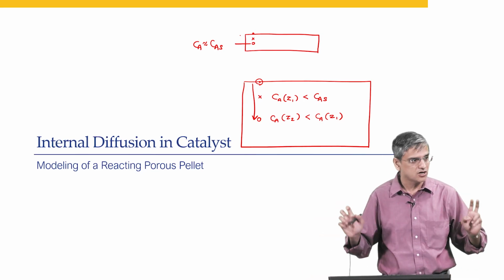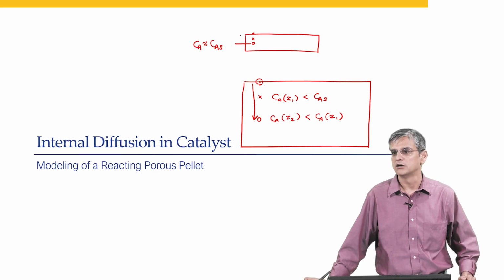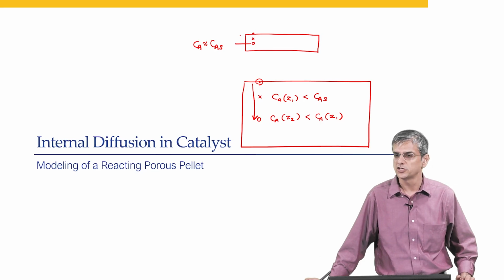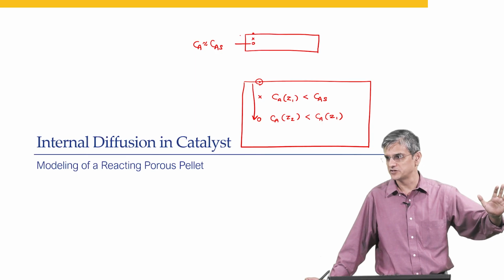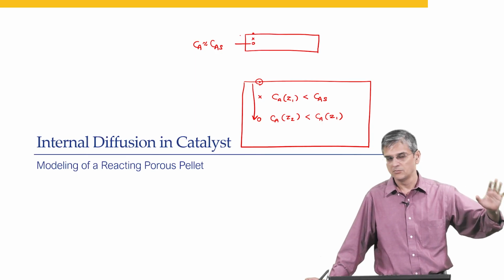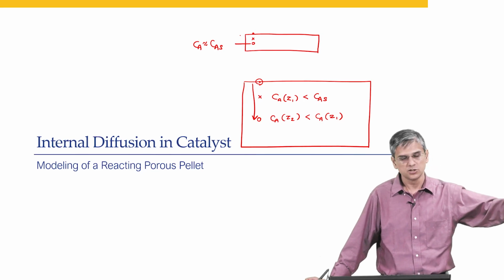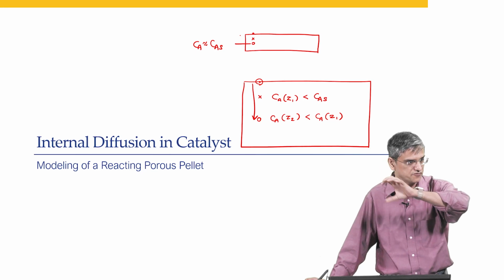Your algorithm is independent of the size. If you were to not do non-dimensionalization, your analysis for a particular geometry will still be independent of the size. But you will have to do one analysis differently for a slab, another analysis differently for a sphere, a third analysis differently for a cylinder.